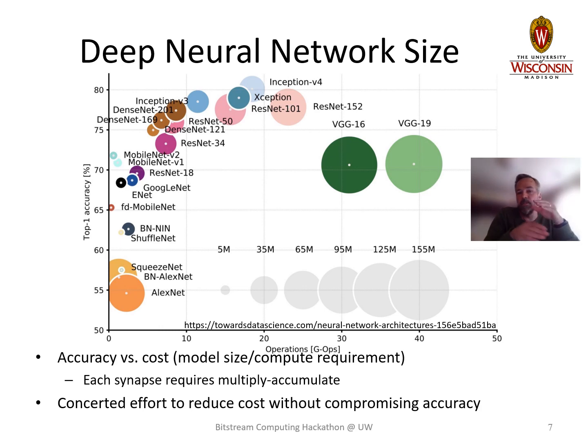This shows a bunch of example networks that have been proposed over the last decade or so, and how they've grown from left to right in terms of the number of operations required, and also the size of the dot, which is the number of parameters, the total number of weights that the model requires in order to operate. You can see that some of these got to be very, very expensive in terms of operations. 40 gigaops means 40 billion operations. 40 billion multiply accumulates have to be performed to evaluate this network for one image.